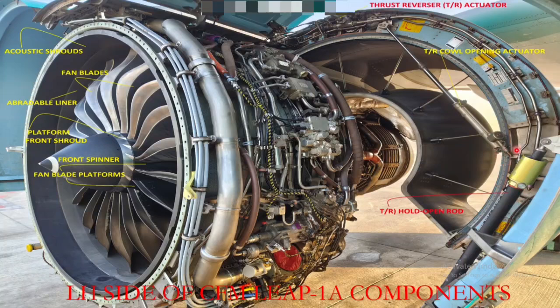Whenever you are using the pump, you will connect here, so the actuator will give support while opening. Make sure the slat is in the retracted position before opening the cowl. This is your TR hold open rod, just to support externally with the fan case. And the rest of the components will go to the next slide.